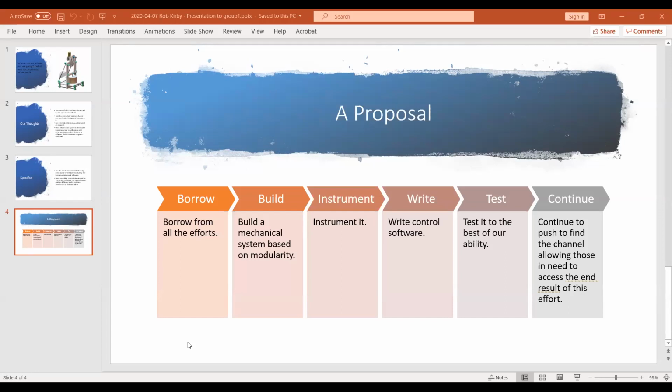Yeah, agreed. There's the medical device industry. You move rather slowly in it. But for a typical medical device, they require IEC 60601 testing, which in itself can be about a 2 or 3 month ordeal, even though they always say 2 weeks. And then there's the design inputs, your quality control system that you're building it under. It's a lot of different things that add cost to the engineering time. Right now, the way we're approaching it, we would be at the very initial stages, called the design planning stage.